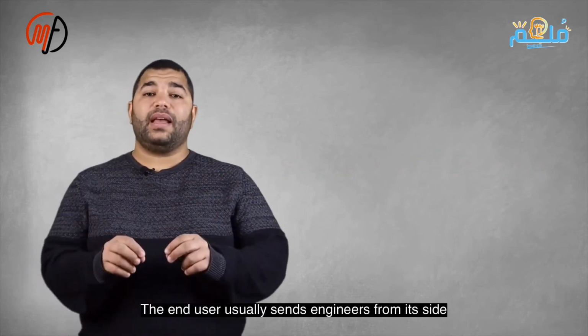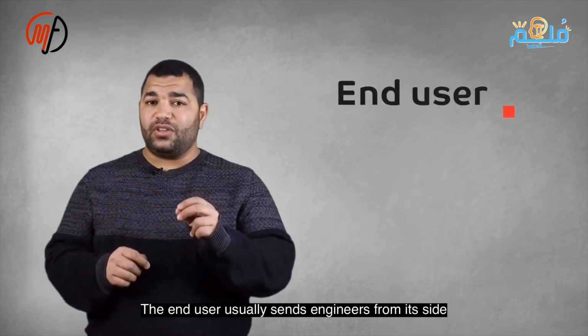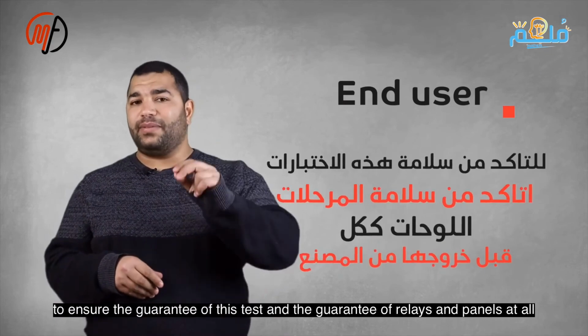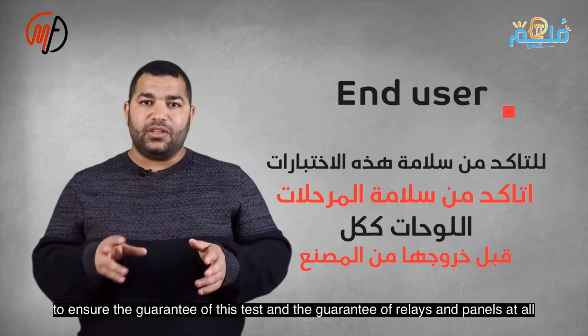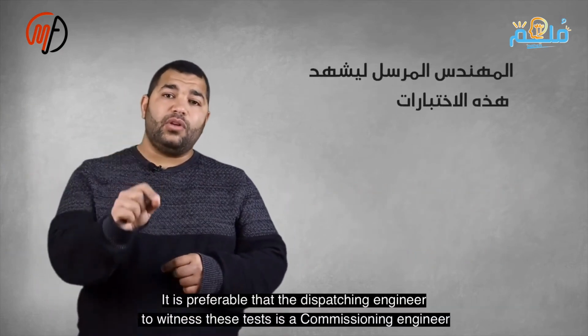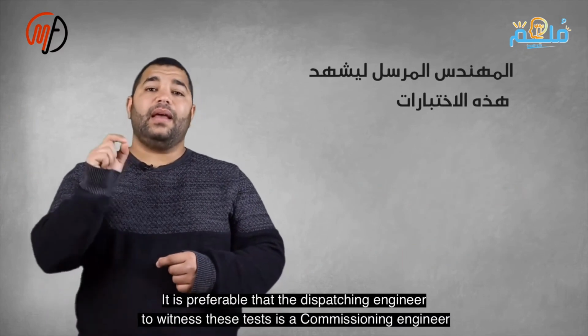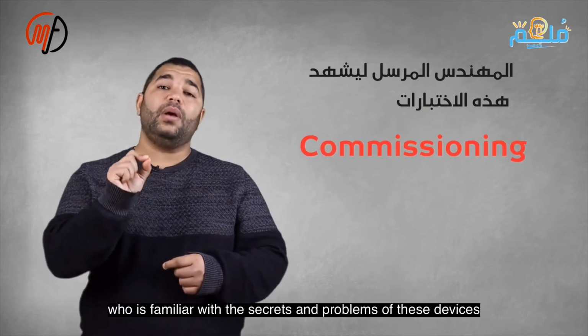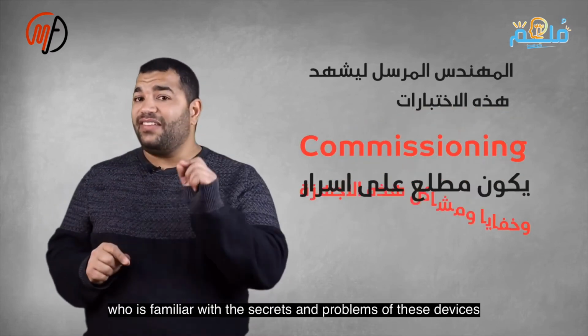Preferably, a commissioning engineer should witness the FAT test as they know the panel intricacies. A common mistake is sending a project engineer, as they may miss details. It is preferable for the engineer accepting this work to be a commissioning engineer, as they know these panels well. Factories aim to meet your needs at the lowest cost, so the right person is essential.